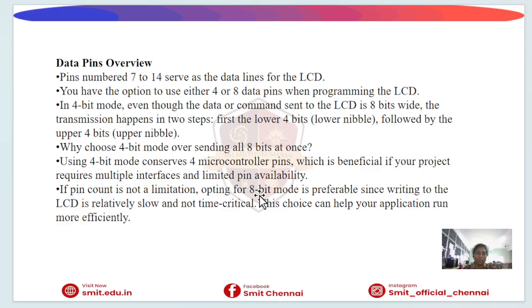The advantage of the 4-bit mode is that it saves 4 microcontroller pins. The advantage of the 8-bit mode is that it is simpler and slightly faster.